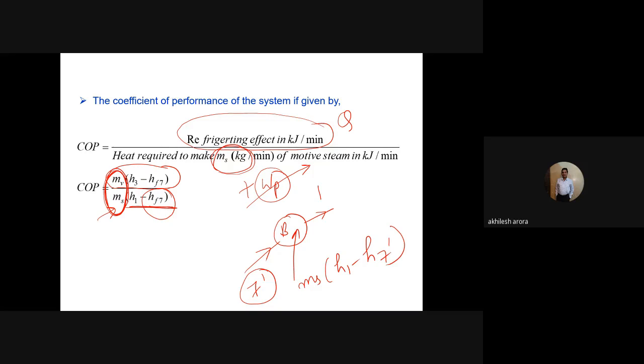सर, फ्लैश चेम्बर से जो पंप हो रहा है, उस पंप का वर्क इसमें ऐड होगा या नहीं होगा? नहीं होगा ना सर? एक्चुअली में क्वांटिटी ऑफ वाटर कम है और उसमें हम कोई ज़्यादा प्रेशर रेज नहीं कर रहे, वो भी नेग्लिजिबल होगा। लेकिन जैसे जो रेफ्रिजरेटिंग इफेक्ट फ्लैश चेम्बर में मिल रहा है, तो बेसिकली वो दूसरा वाला सर्किट है जो पंप ले जा रहा है, वो सेकेंडरी सर्किट हुआ ना, उसका तो वर्क वैसे भी कंसिडर नहीं करना चाहिए।